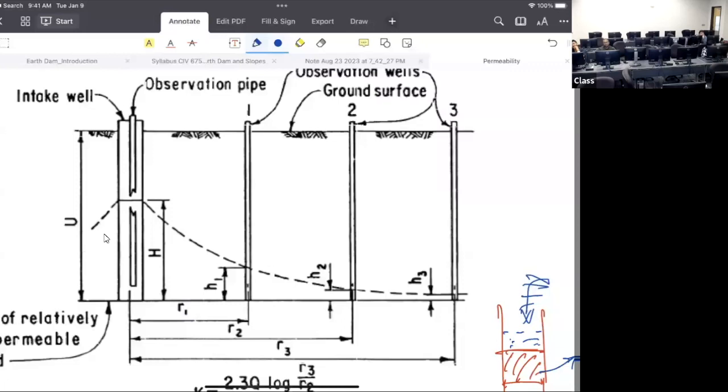Let me give you an example. In Mississippi, you have expansive soil with cracks on top, and water builds up, but after a certain time the permeability stops, right? It behaves like a barrier. And then it's a highly plastic soil. Now all the water is coming in, and the soil is becoming softer. You can take a very highly compacted clay, soak it in water, and then take it out. What's going to happen?